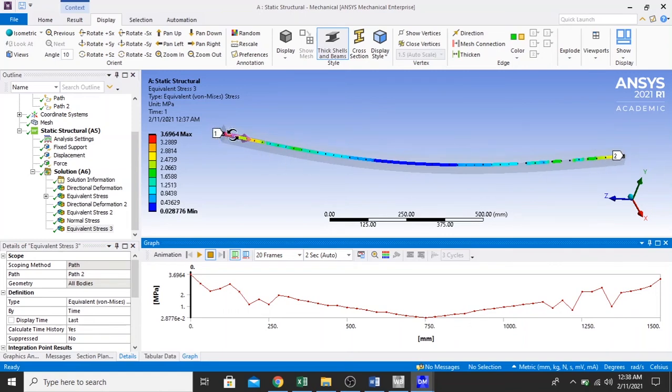So that's why the color there is represented by a red color. So there is a little bit of difference in the finite element analysis: the top surface will be colored in red, and the value of the equivalent stress right there is the highest, because it contacts directly with the force. So there is a little more tension in the top surface and the bottom surface rather than in the middle position of the model.